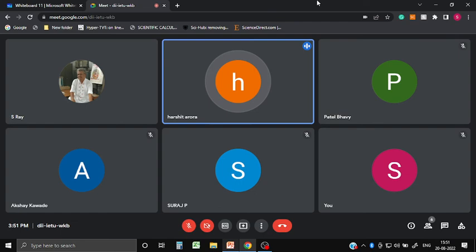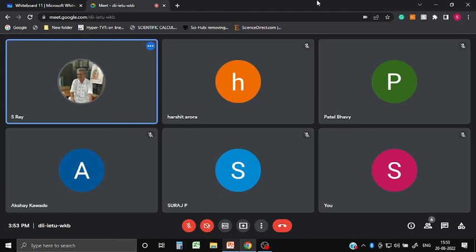Normally, the pressure control system is exactly the same. At least that is what my practical experience has shown. But the valve on the hot bypass line to control the submergence is usually fitted with a globe valve, and it is not that you manipulate it as a tool to control or regulate the pressure in a regular fashion. It is typically kept about 40% open.